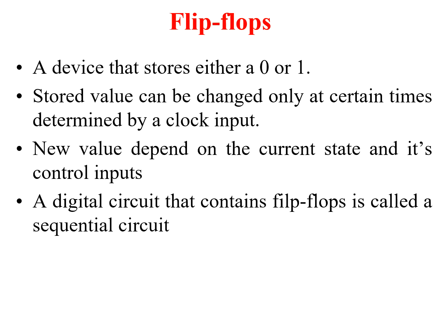And next is a flip-flop. A device that stores a value, either 0 or 1, is called a flip-flop. Its stored value can be changed only at certain times determined by a clock input. The new value depends on the current state and its control inputs. A digital circuit that contains flip-flops is called a sequential circuit.